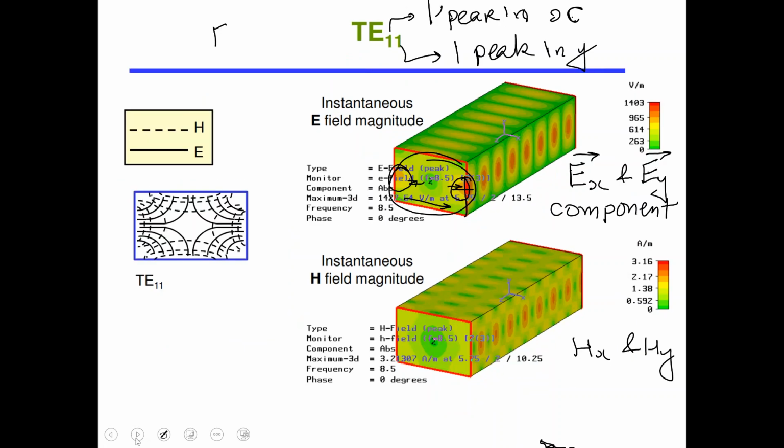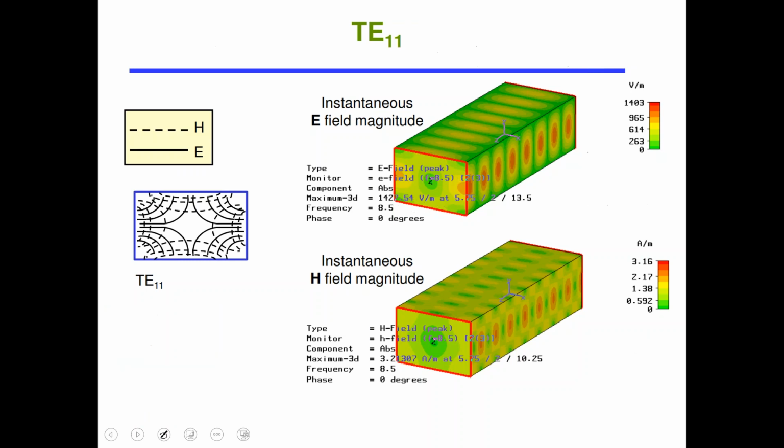As you go to higher modes, the energy is being pulled towards the sides, towards the edges of the waveguides. It's not going through the center. Part of the energy is getting pulled towards the sides, and it's not going to be a simple monotonic function. If you look at the energy distribution, you're going to have peaks and troughs in different parts. In fact, the zero energy is going to be carried somewhere here, somewhere here in the center, there's not going to be much energy being carried, because the electric field over there is going to be zero.